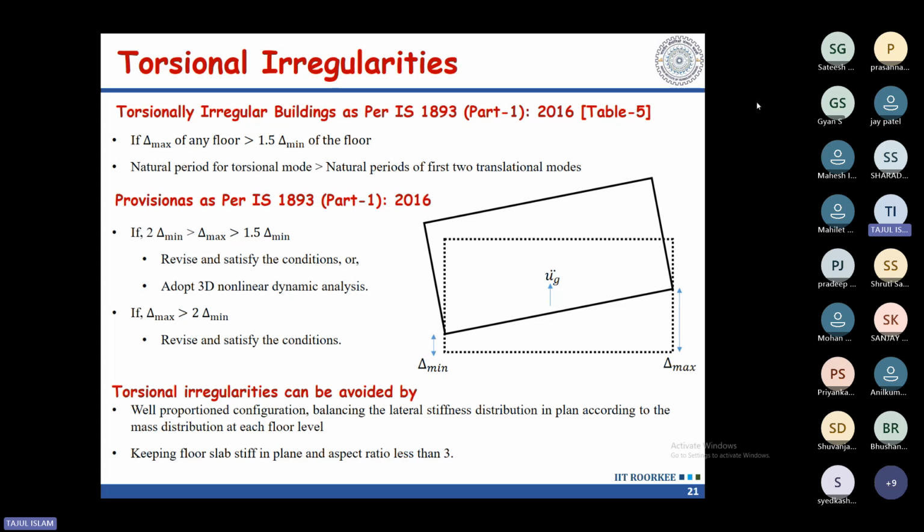Another thing is, if you know the information about the site, like the VS30 parameter for the site where you are going to construct your building, then you know the magnitude of the expected earthquake. If you know these parameters, then you can go to the PEER time history database. This is one of the widely used databases. Spelling is P-E-E-R.